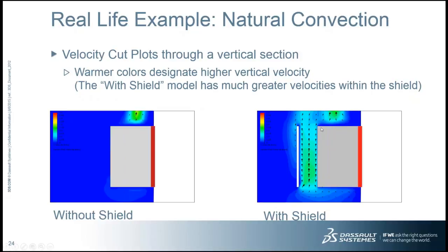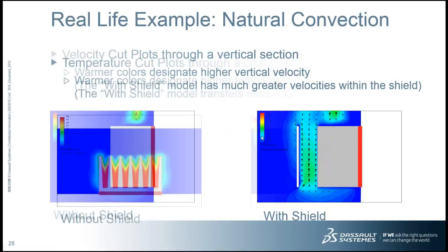And here you can see just a slice through the center of this guy. We have this air flowing through here as the hot air rises, and on this side we don't have as much of that airflow. We still have the same airflow between the fins, but now with this area enclosed somewhat, creating a little bit of a Bernoulli effect.